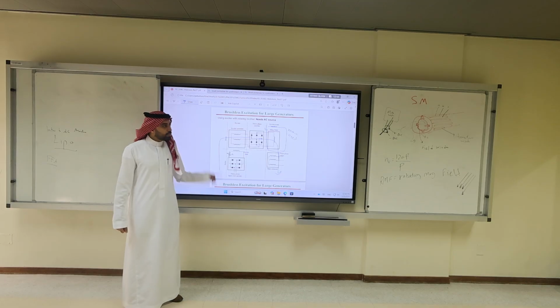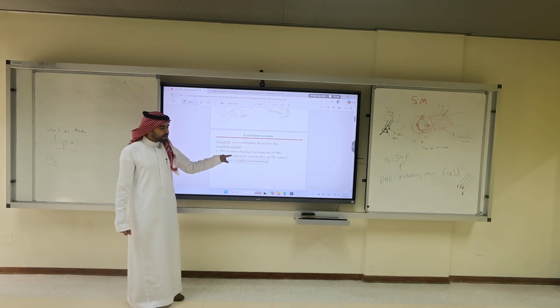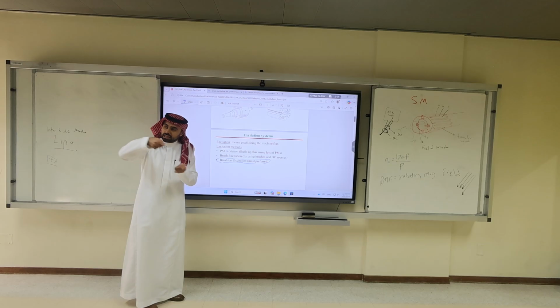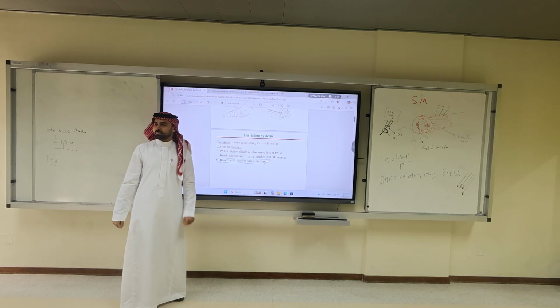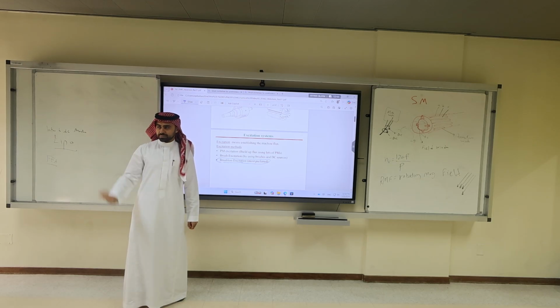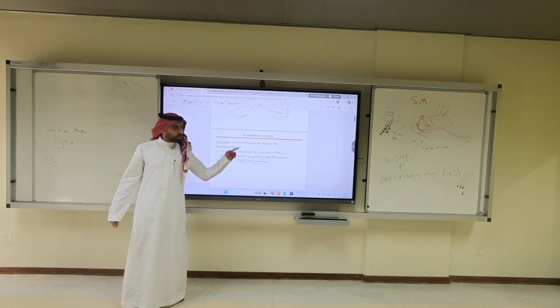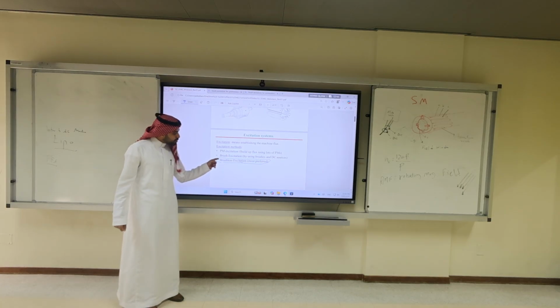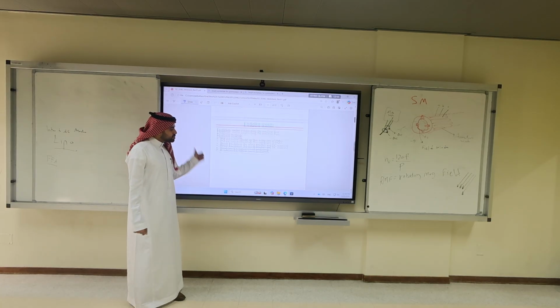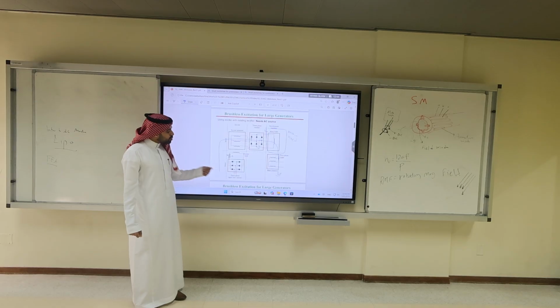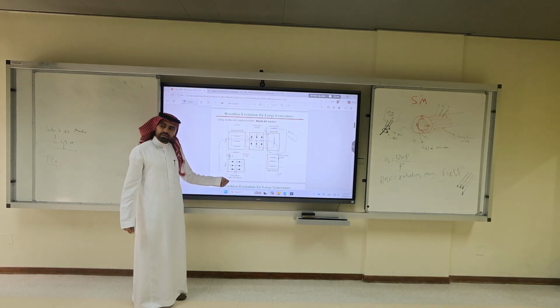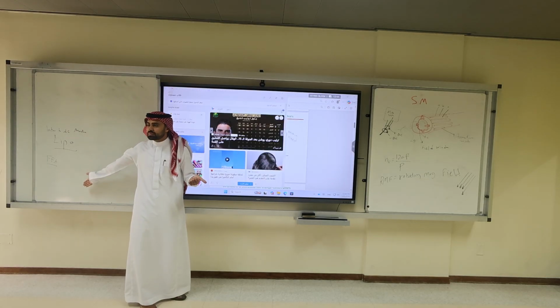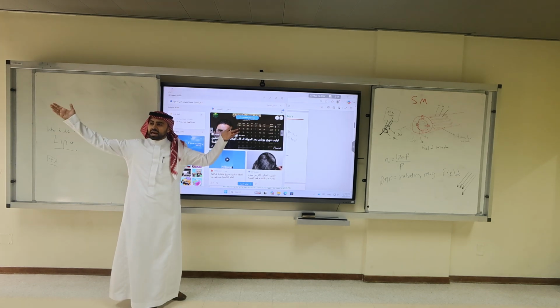You don't put in brush excitation, your input on the rotor is a DC source through slip ring. No rectifiers. But I told you this method is not durable because of the brushes. So your input for the brushless excitation, the most preferred method, is a small three-phase, maybe 120 volts. This is small for a 10 kV generator.